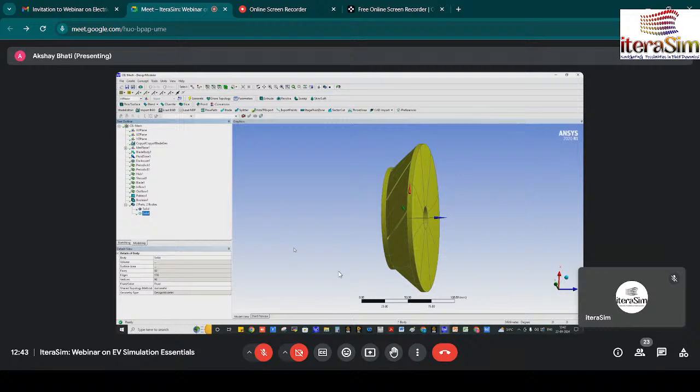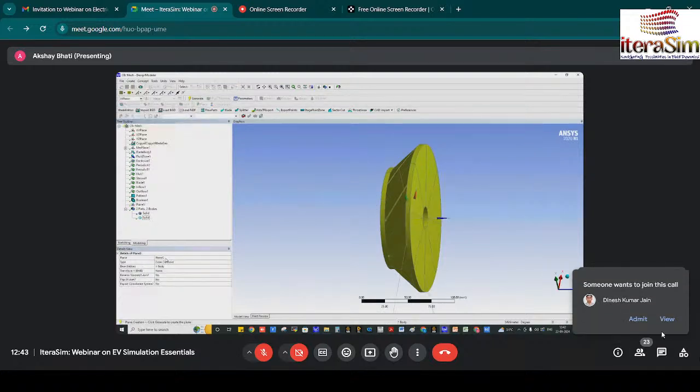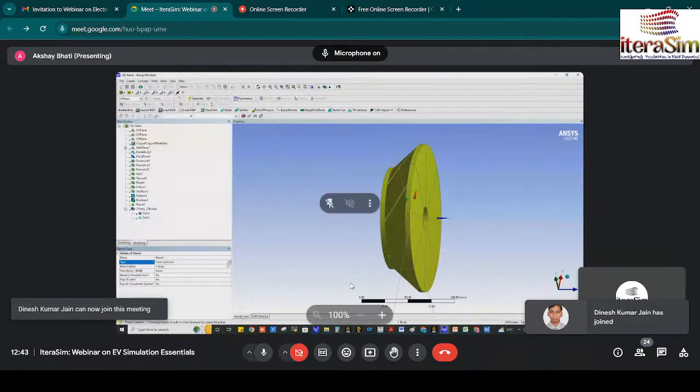But if you go for CFD simulation of that blade, we will rotate only the fan part. The inlet part and outlet part need not be rotated. So first we need to separate the body into three segments: one is the inlet part, one is the fan domain, and another is the outlet part. For that, first we will create a new plane.